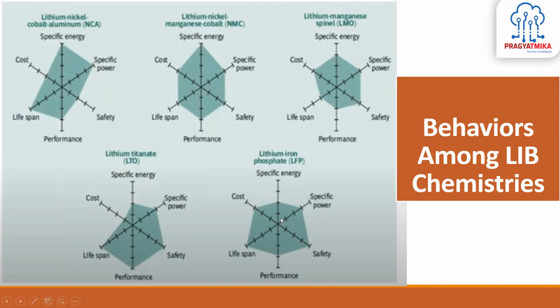LFP pack has less density, but on the part of safety, it is thought to be good, because we have approximately a 10-degree advantage in the working conditions. Like for the NMC, it is 25 to 40 degrees centigrade, or 45 degrees centigrade. Some people use it with excess cooling mechanisms for the performing battery packs. So LFP can go up to 50-55 centigrade by those means. So that's the 10-degree advantage we have, and many people are advocating this chemistry for warmer temperature zones. But